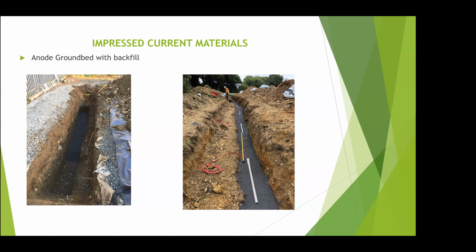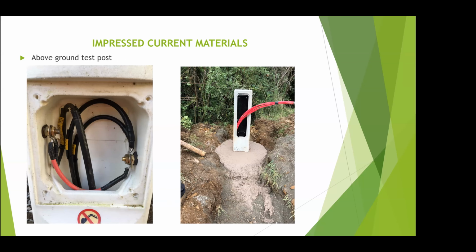And then the red cables here, they sit on this little shelf, and then the backfill would be filled over the top of those. And these cables would then run to a test post, so you could connect them to your power supply, and the power supply would be connected to the pipe as well. This is an above ground test post, and here you can see where the cables are coming into terminals inside, and they would be connected and distributed to other areas.